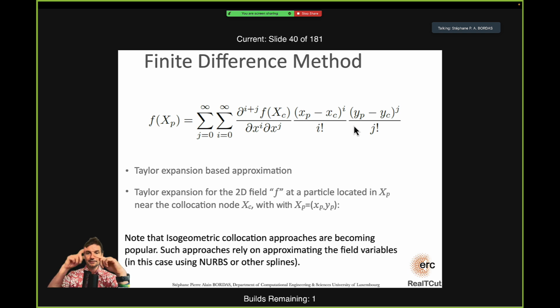If you have a very strong gradient, then the collocation method from that standpoint will not work, because you have a Taylor series expansion, which is a polynomial function, trying to approximate a jump or a singular function, and of course we know that doesn't work, and you are faced with the problem of the Gibbs phenomenon. So this is not what you should do.